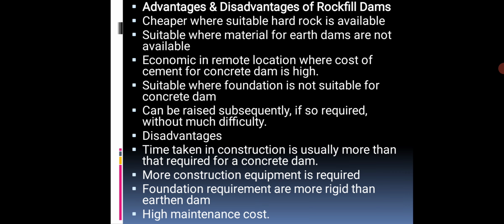Next, these are the advantages and disadvantages of rockfill dams. First one, cheaper where suitable hard rock is available. Suitable where material for earth dams is not available. Economical in a remote location where the cost of cement for concrete dams is high. Suitable where the foundation is not suitable for concrete dams. Can be raised subsequently if so required without much difficulty. Next, disadvantages. Time taken for construction is usually more than that required for a concrete dam. More construction equipment is required. The foundation requirements are more rigid than for earthen dams. High maintenance cost.